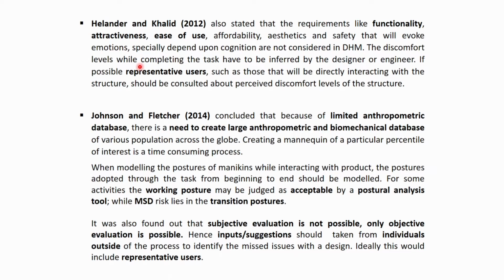So while designers or engineers are designing a particular product, workstation or any other facility, evaluation through digital human modeling software is okay, but at the same time it will be good if we can take feedback from representative users, because subjective evaluation is not possible with the software. Aspects like affordability, aesthetics and safety, which are related to the cognitive aspects of human beings, can be evaluated with the representative user population. With the help of a small representative user population, we can evaluate the overall concept model. Initially, we can evaluate with the digital human modeling software to find out anthropometric or biomechanical compatibility, but for various subjective evaluation purposes, we can call for representative users.